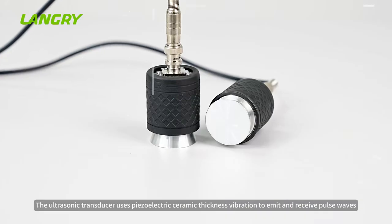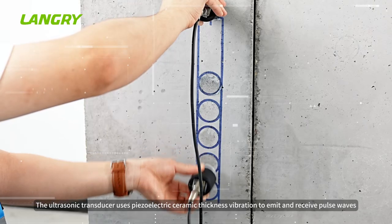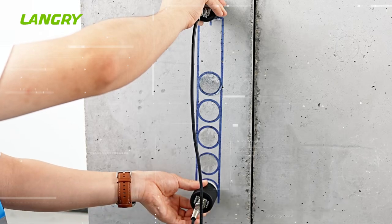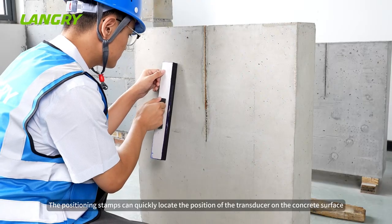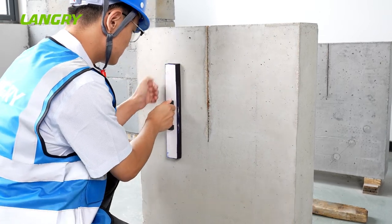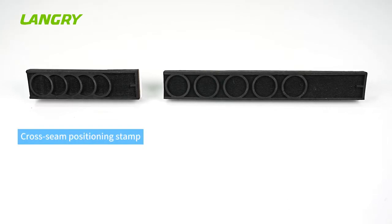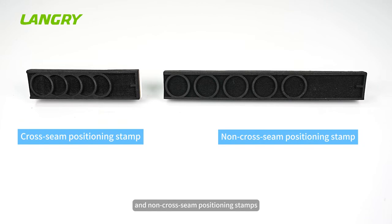The ultrasonic transducer uses piezoelectric ceramic thickness vibration to emit and receive pulse waves. The positioning stamps can quickly locate the position of the transducer on the concrete surface. The stamps are divided into cross-seam positioning stamps and non-cross-seam positioning stamps, which need to be used together.